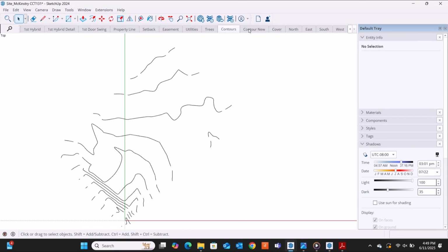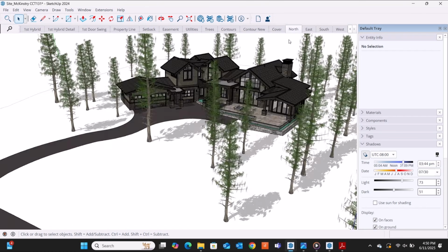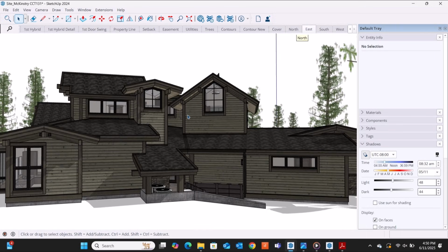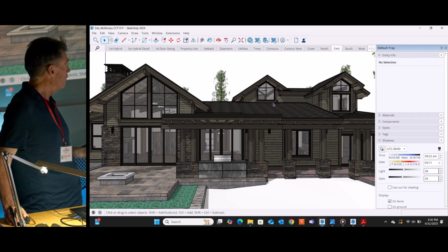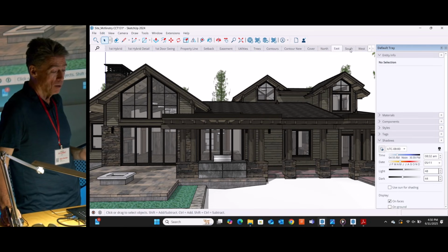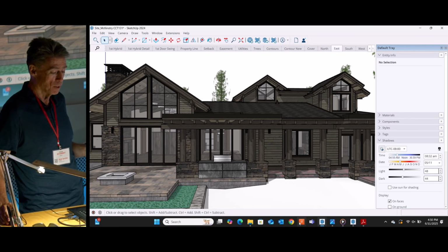It's very simple. A lot of people struggle with that concept and try to just align it in layout, which will kill your budget. And then early in design, before I go to a render, I still have some basic views saved because I'll present the perspectives directly out of SketchUp on the drawing sheets. Once it gets into design development, I do switch. I'm using D5 render now, and those become more solid renderings.